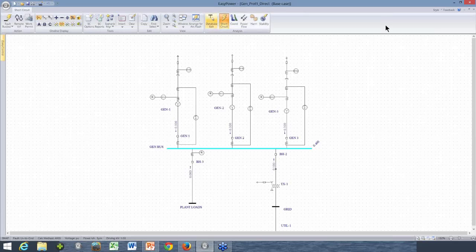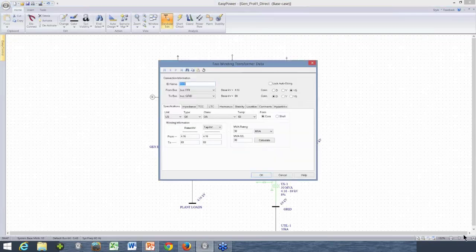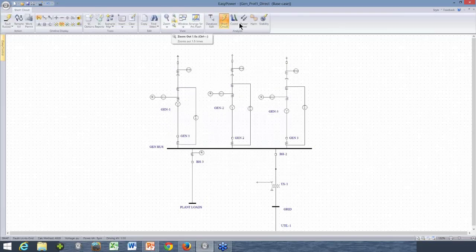All right, so if I go back to the database, let's take a look. If I were to get rid of this grounding resistor and go to solid grounding, so now I have a solidly grounded Y here, and this is a delta. This is going to be a ground source for my 4160 volt system here. So now when I go back to short circuit, on line to ground, when I fault this bus, now instead of 400 amps, I get 63,000 amps.